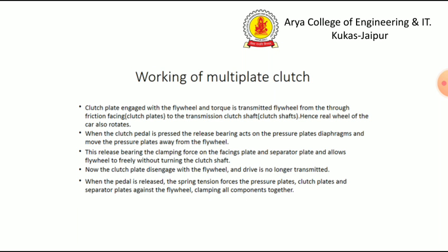When the pedal is released, the spring tension forces the pressure plates, the clutch plates and the separator plates against the flywheel, clamping all components together, and again starts transmitting the torque.